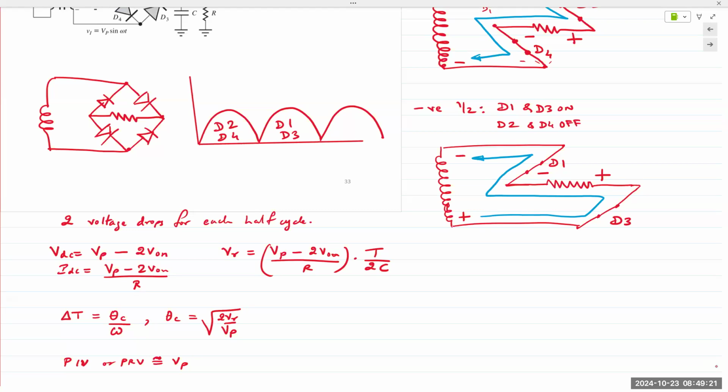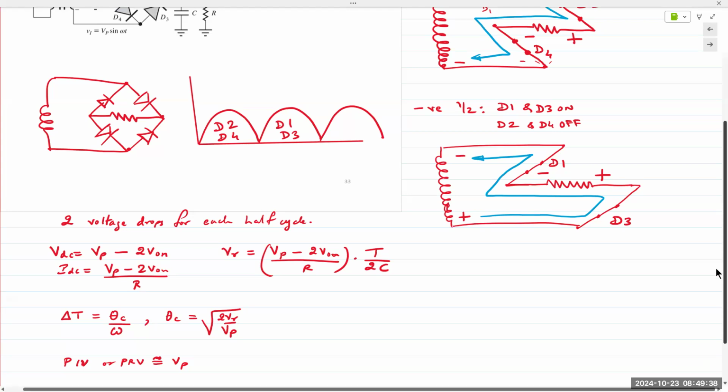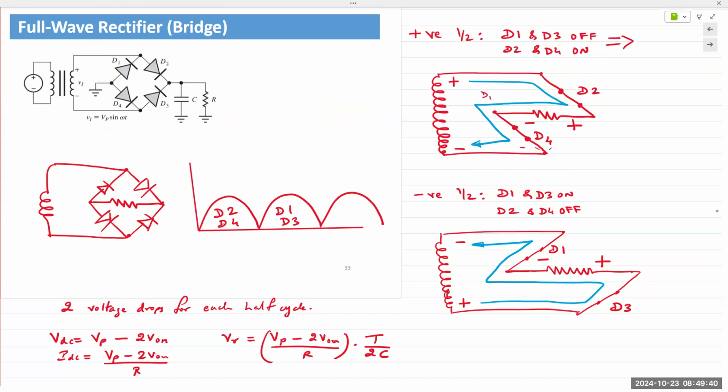Yes. You said the devices will work in other countries for their different voltage levels, but what about the different frequencies? It can handle 50 to 60 hertz easily, just fine. Because again, if you look at the rectifier circuits, if the frequency is 50 hertz, 60 hertz, 100 hertz, 1000 hertz, doesn't really matter, as long as the diode can switch fast enough, and these regular rectifier diodes can.